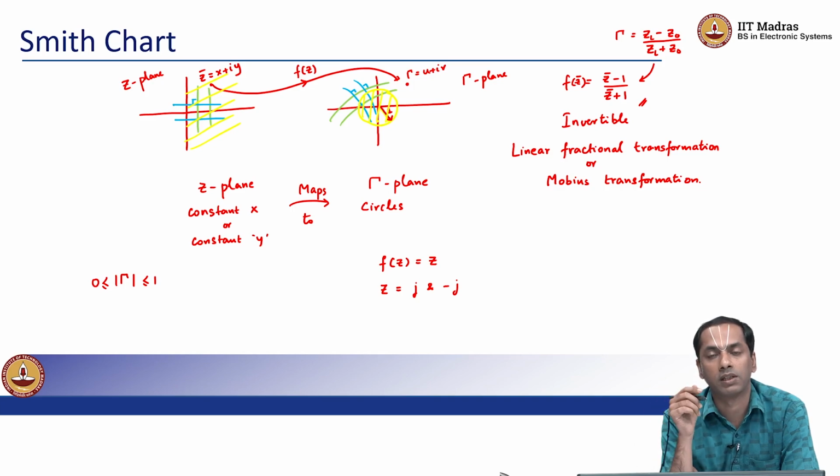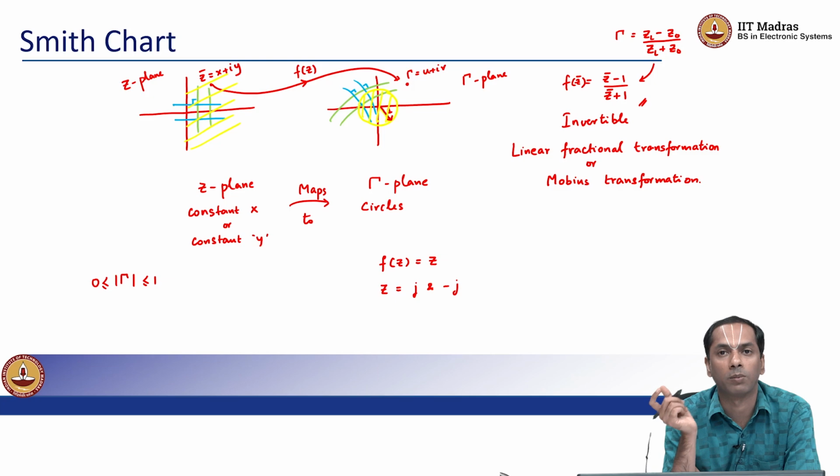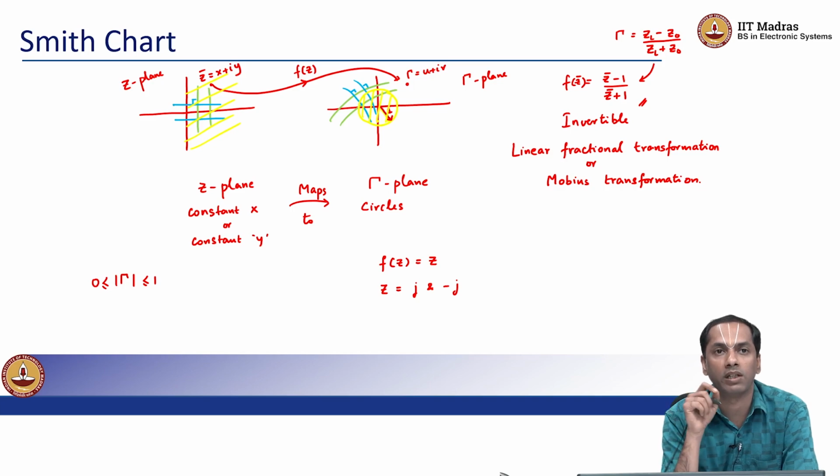with respect to a characteristic line impedance. So I take the impedance, normalize it to the characteristic impedance, and if I want to find out what reflection coefficient that particular load will have, then I just look at the gamma plane and look at the gamma value to get the complex gamma value directly. And since the mapping is 1 to 1, every point within this unit circle corresponds to a very unique load, a combination of R, L or C to give me that particular reflection coefficient.